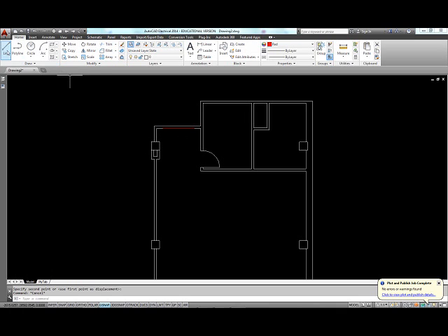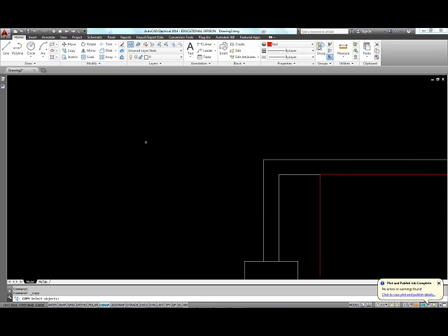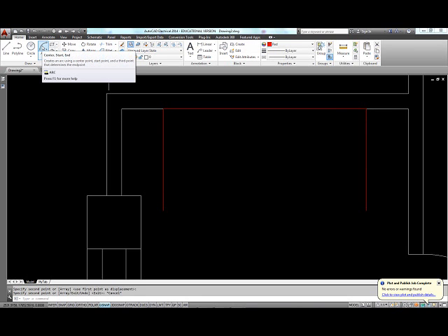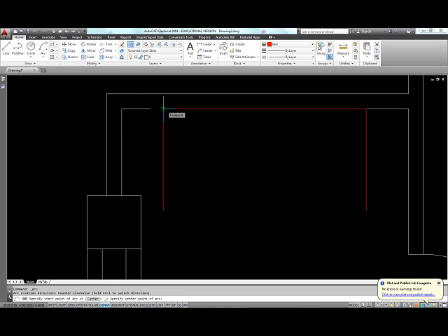Each one of them is going to be 95 centimeters. So let's make a line here, and at this end at 0x direction and minus 950 millimeters. And then we'll use the copy command. We'll copy this object from this end to this end. And let's do the same thing as before. Two arcs. This is the center, starting from here and ending there. Do it again.